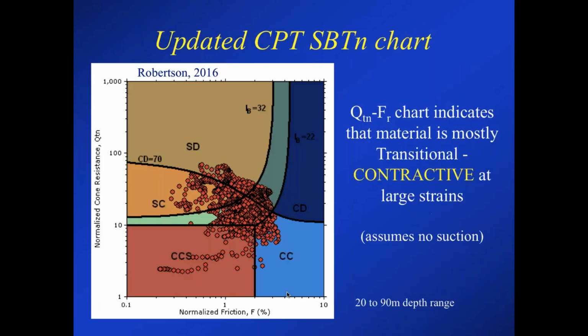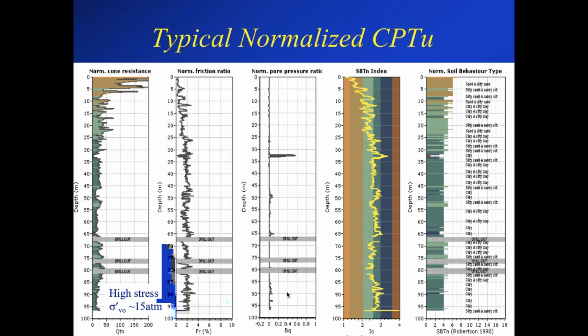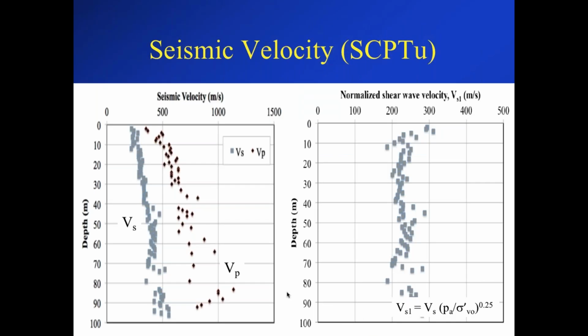And so that's how they're able to get all of those data points. Sorry, where is the curve? Right here. They're basically stopping every meter, and you can see there's lots of data points. And so they're able to determine the shear wave velocity every meter interval as they progress in the penetration.